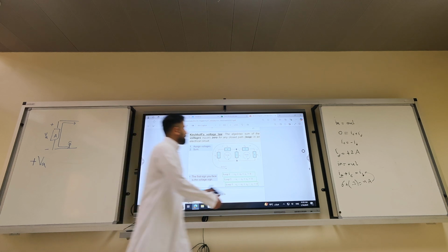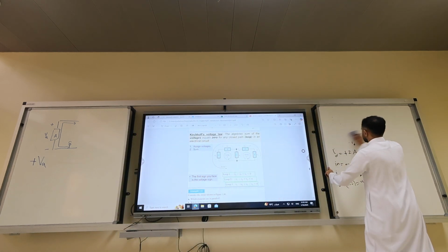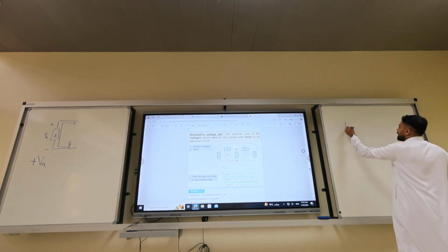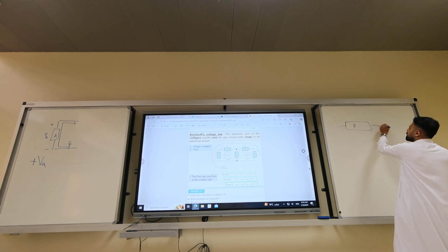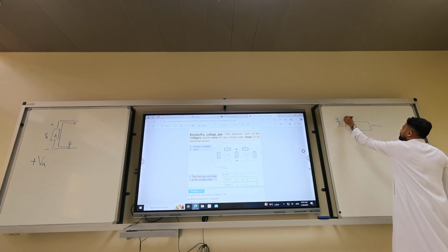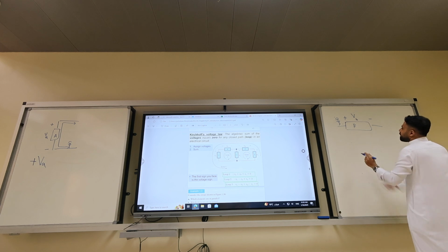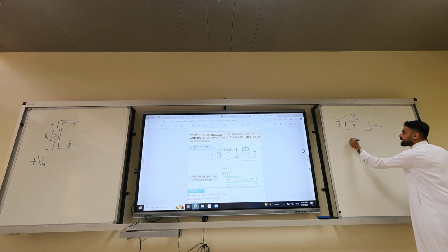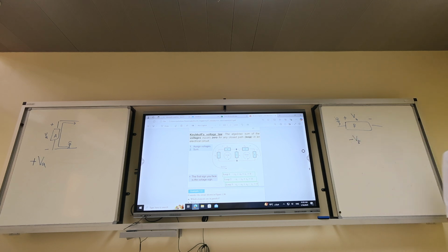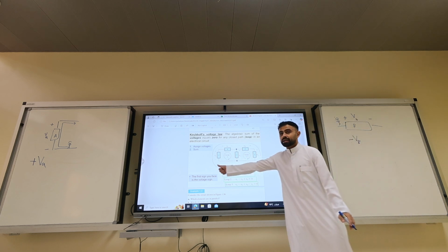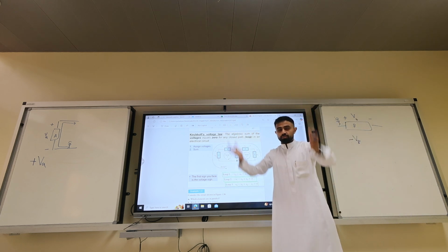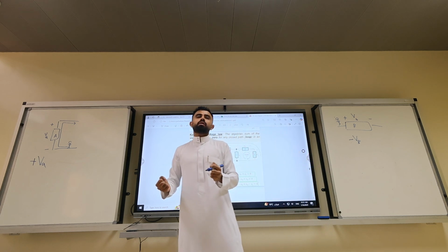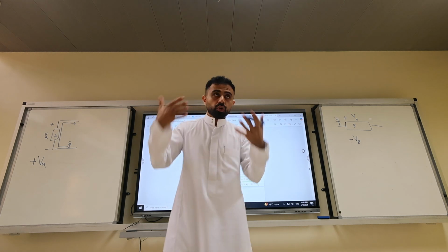Now, let's say I'm at an element B. So this is me, I finished walking over element A, I'm walking at element B. And this is me. Plus minus, we call this VB. Am I experiencing a voltage rise or voltage drop? Drop. So I say minus VB. So if you experience a voltage rise, you add a rise. You're gaining voltage. If you experience a voltage drop, you lose voltage.